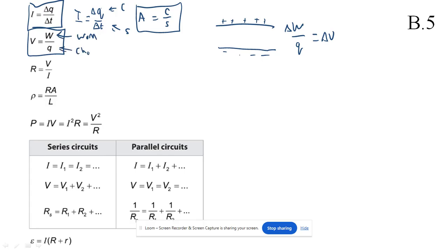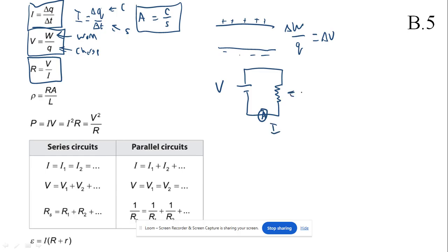That's charge. This is Ohm's law. So the resistance, if I have a particular voltage, I should draw an IV resistor. I'm sorry. All right. If I've got some voltage here and then I have an ammeter here, and I measure the current, the resistance of this thing is just the voltage divided by the current. So if a lot of current flows, the resistance must be low. If it takes a lot of voltage to get it to flow a given amount of current, then the resistance must be high. It's Ohm's law.